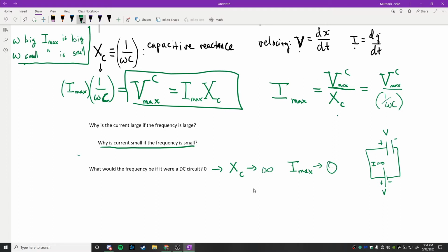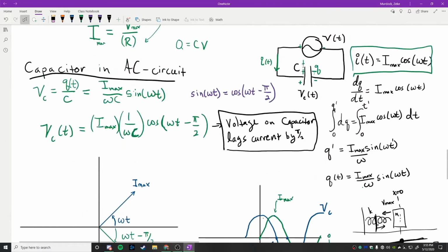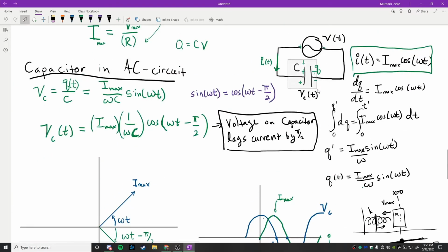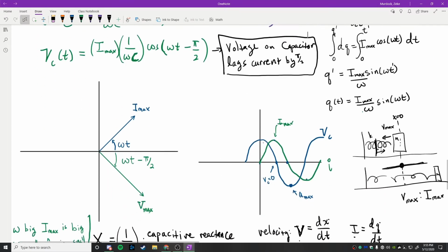If you have a low frequency, you have a longer time, that's what he's saying, a longer time to store the charges, which means the capacitor is going to do more, right? The capacitor does the most work in the system, or has the most effect on the system, when it's allowed to be fully charged. And if the system is charging up slowly, because the frequency is slow, then the capacitor is going to build up that kind of opposite EMF more quickly. And once the capacitor is fully charged, well, that's like the compressed spring, and it's going to start pushing back on you.